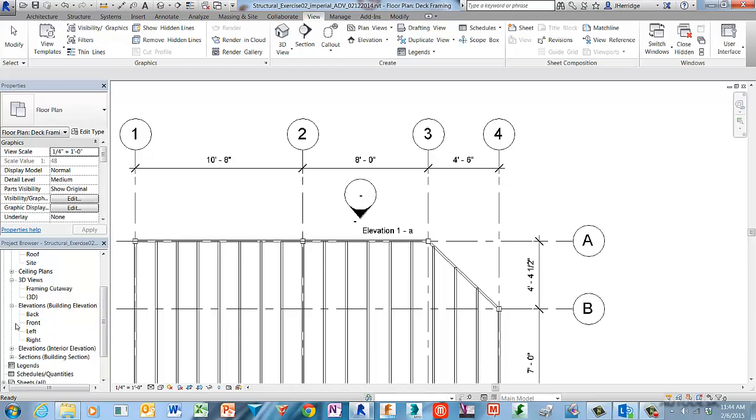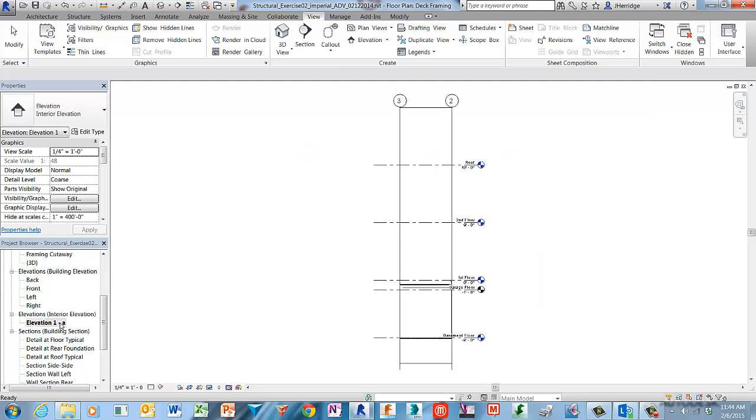Okay, so the elevation marker is now permanent, and the question is, where is the elevation view stored in Project Browser? So if we look at the stock elevation views, it's not located there. And just confirming it's not a section type, but let's go in the other elevation folder, and there it is. So go ahead and double left click to open up the framing elevation.